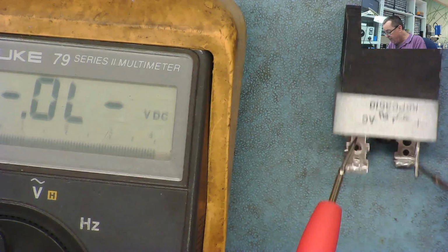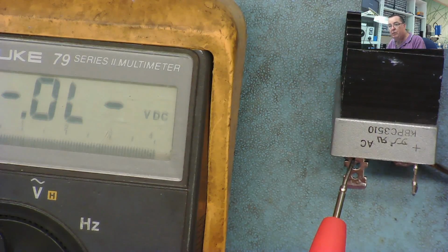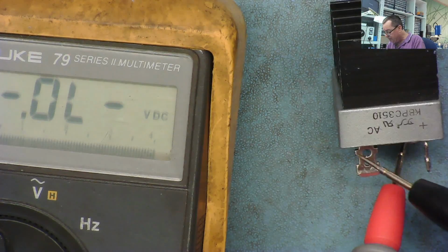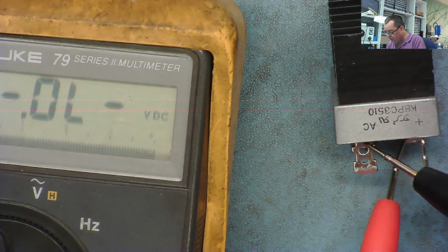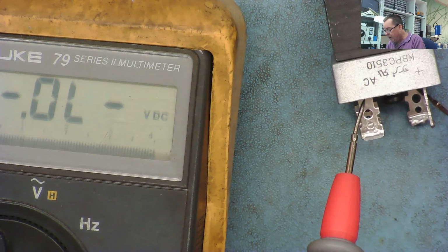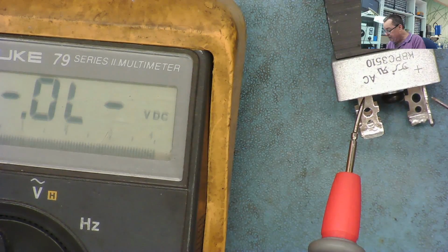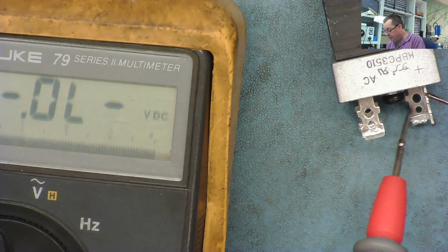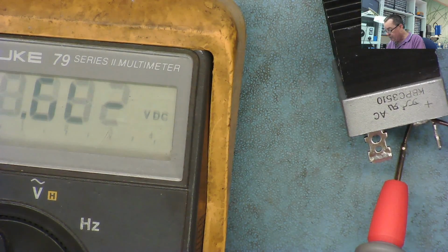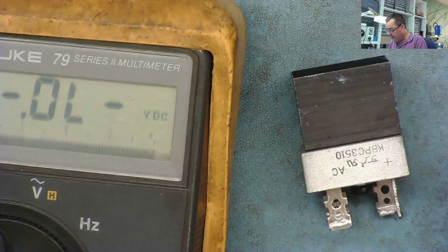So if we know this is one AC, the other AC will not conduct in either direction. Yeah, it doesn't conduct with it that way round. It doesn't conduct with it this way round. So we know those, if it's a good diode, those are the AC. If this is the positive, this should conduct. Yeah? And then this should be the other AC, and it conducts. We know this is positive. Yeah? So we've got it.